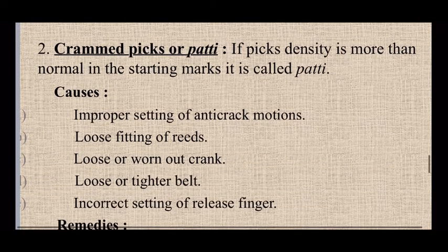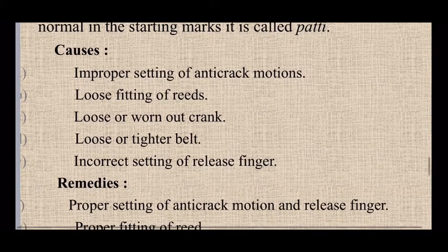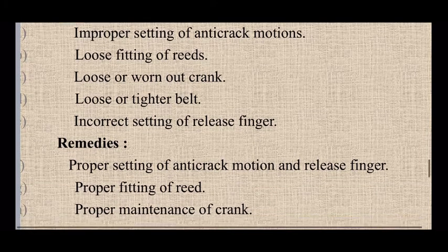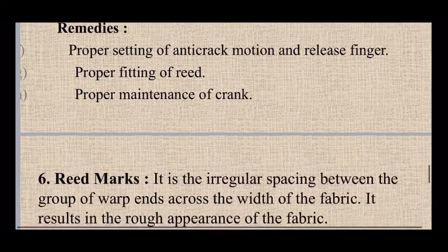Causes are improper settings of anti-crack motion, loose fitting of reeds, loose or worn out crank, loose or tight belt, incorrect setting of release finger. So remedies are proper settings of anti-crack motion and release finger, proper fitting of reed, proper maintenance of crank.